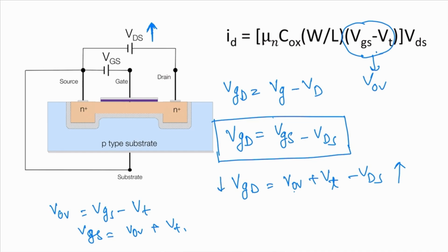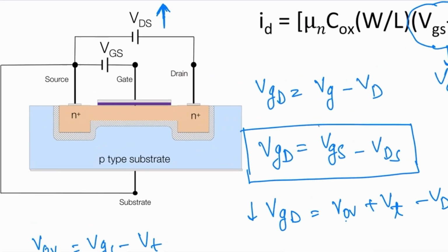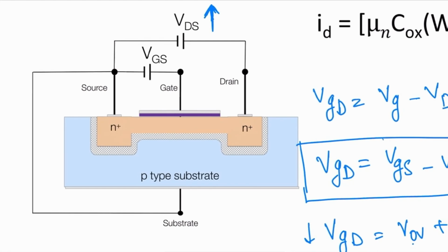So just now, for the sake of simplicity, just focus on this one. This is the n-type semiconductor and this is the p-type semiconductor. You are applying a voltage source on the drain to source terminal. Source and substrate are connected. That means you are connecting a voltage source here in the drain terminal and directly to the substrate terminal.